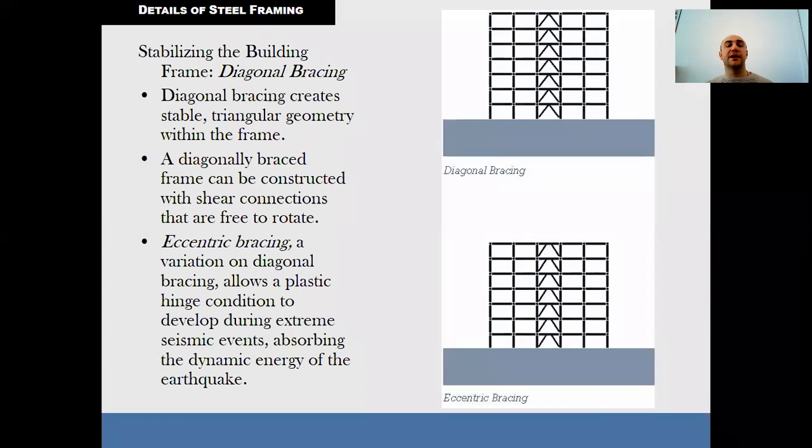Horizontal bracing needs to be located at each level, however the floor system itself may provide sufficient resistance. That's why roofs and coverings may require bracing more often than traditional floor levels.